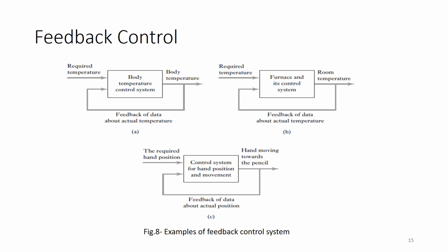So your system will be having number of losses, frictional losses will be there, time losses will be there. Okay, so we don't know, if we are not considering those, then your actual movement will be very less as you have calculated. So we need to put a feedback system such that whatever input I am getting, either the output is also that much or not. If it is not, then it should again move a little further to compensate that loss, or it should retard back if it has moved further.